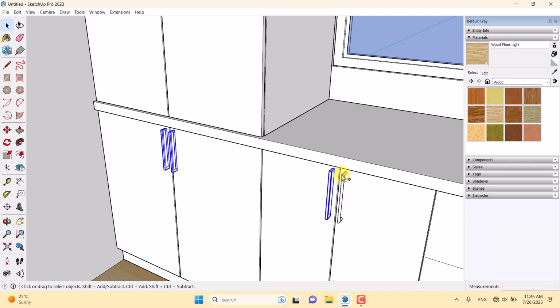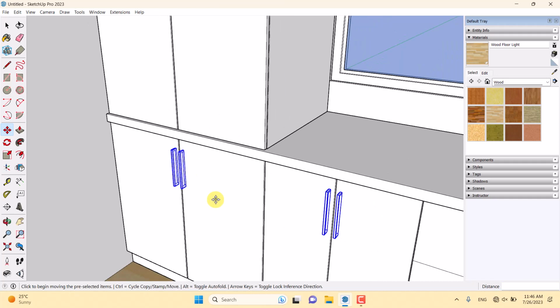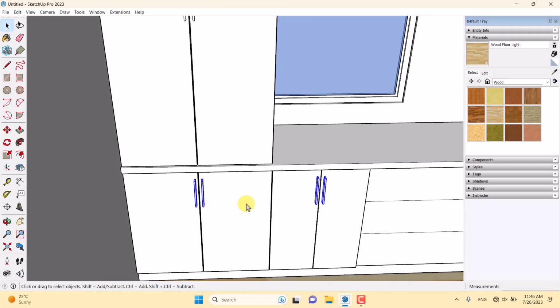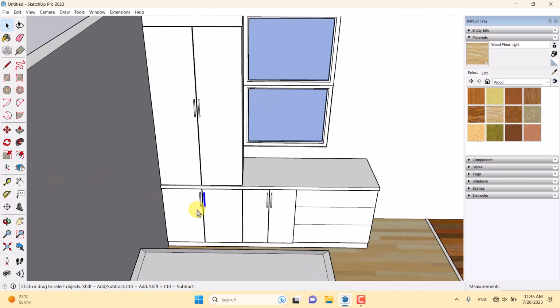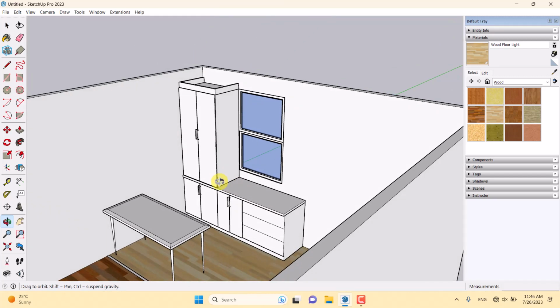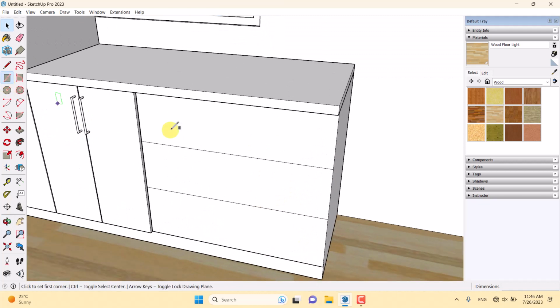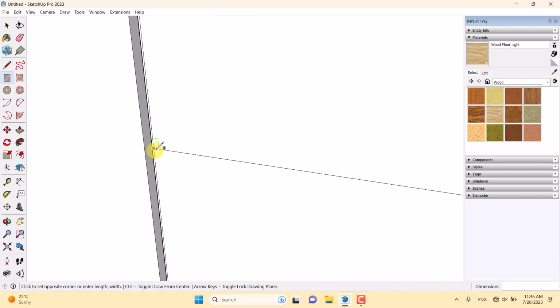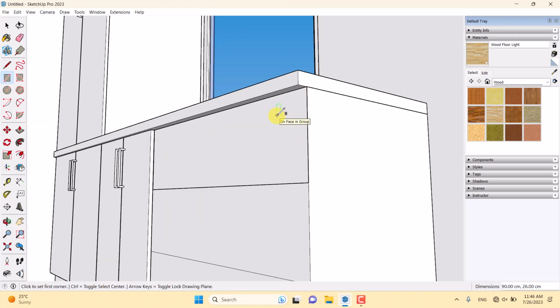And I need some distance about 0.4 in each opener in here. So I can use this handle, press the rotate option, press Ctrl on my keyboard and take some rotate copy about 90-degree angle and press enter. Now I can move it in this place and adjust it at the center point.